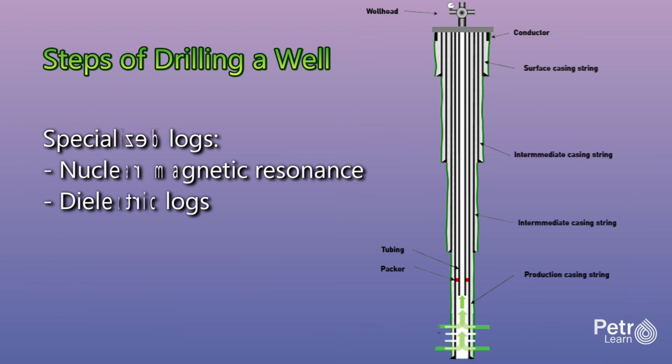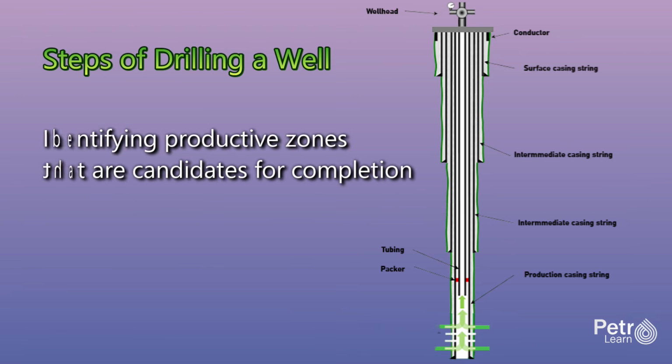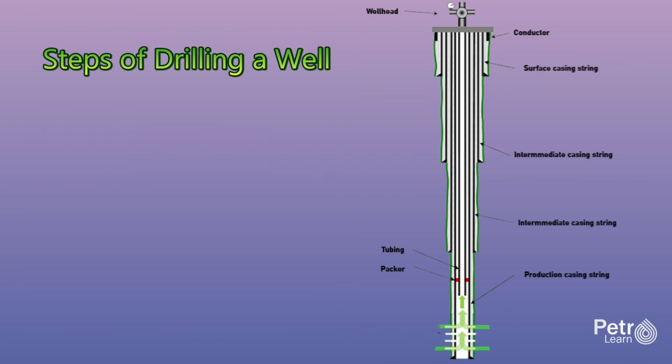Additional specialized logs may be run, including nuclear magnetic resonance, which measures pore size distribution and flow properties, and dielectric logs, which can distinguish oil from water in formations with very salty drilling mud. The logging data is analyzed in real time by the logging engineer and petrophysicist. They identify zones with good porosity, high resistivity indicating hydrocarbons, and sufficient thickness to be commercially productive. These zones are candidates for completion.